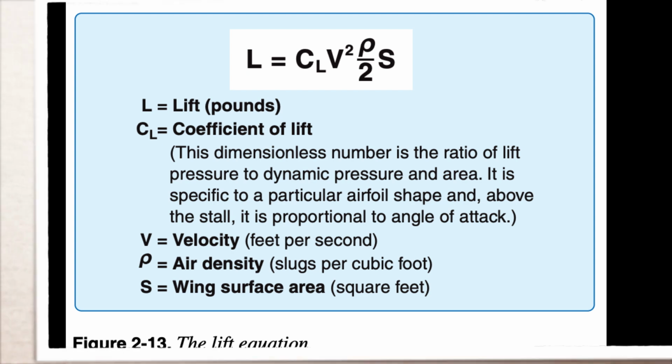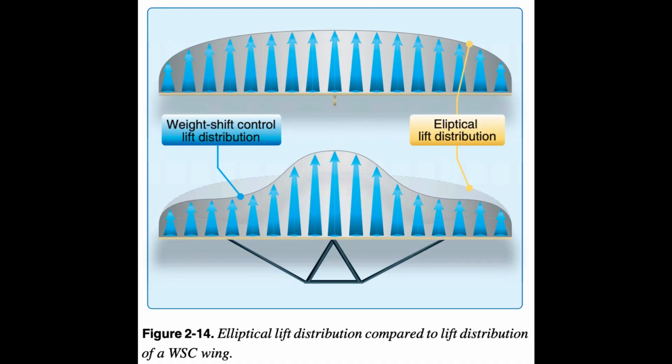All wings produce lift in two ways. 1. Airfoil shape creates a higher velocity over the top of the wing and a lower velocity over the bottom of the wing with Bernoulli's Venturi effect. 2. Downward deflection of airflow because of the curvature of the wing with the principle of Newton's third law of motion: for every action, there is an equal and opposite reaction. Both principles determine the lifting force. Review the Pilot's Handbook of Aeronautical Knowledge to understand Newton's laws of motion and Bernoulli's Venturi effect.